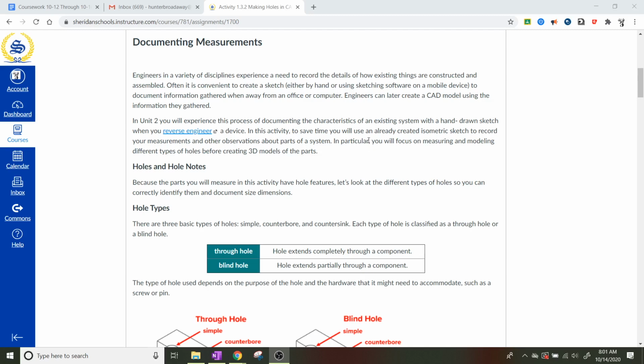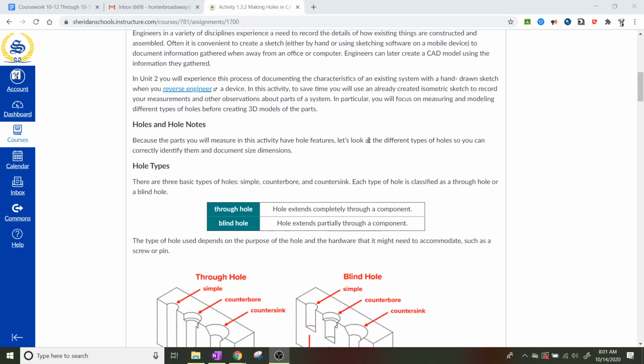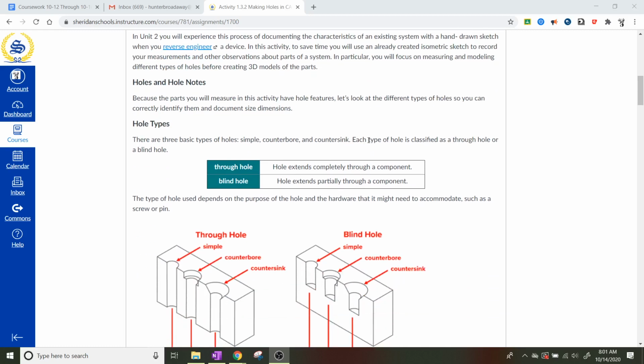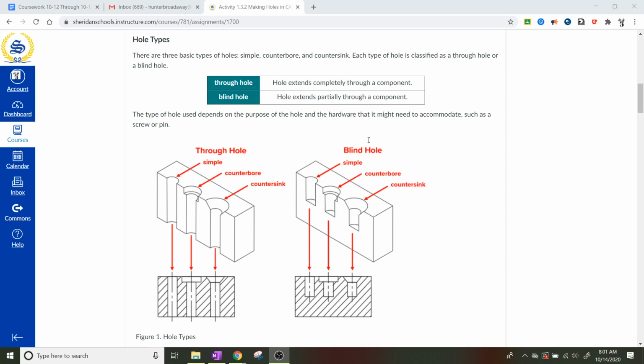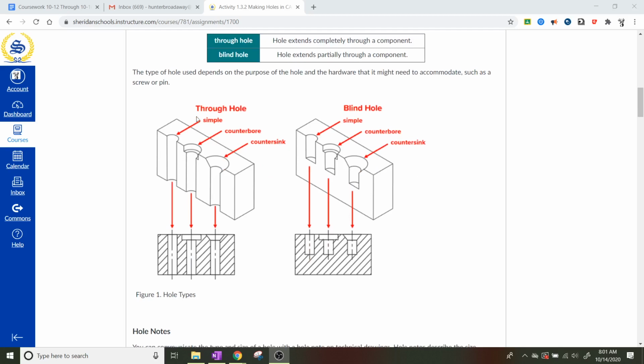Today we're going to specifically focus on holes themselves. Holes are basically whenever you have a circular, round cut that goes through an object. There are two different types of holes on face value: a through hole, and a blind hole. In the examples I have here, a through hole is whenever you take a drill and pass it straight through a piece of plywood or MDF, and you can see the other side. If you can see through the material, then it is a through hole.